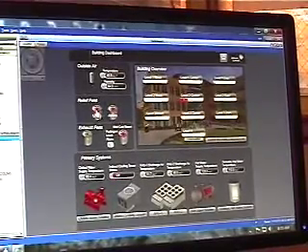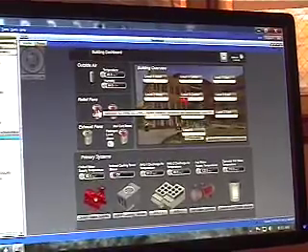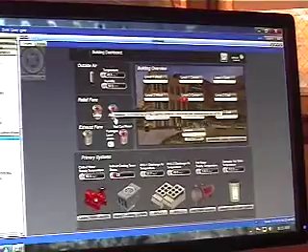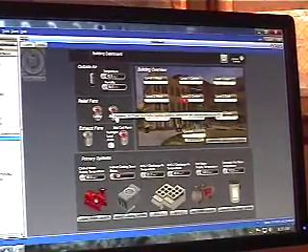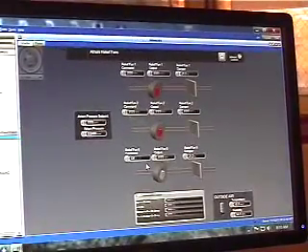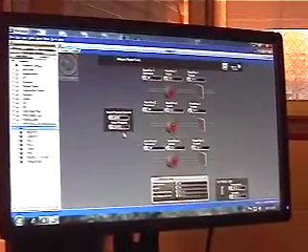Keep going down here. With your relief fans, there's two different sets of relief fans: the lobby set and then the atrium set. The atrium has 3 exhaust fans tied to it, and they all run together. What we're trying to do is, you're going to have the 2 sides of the building. The lobby is the west side, and the atrium is the big open area. So you have an atrium set point, and then you also have a lobby set point.